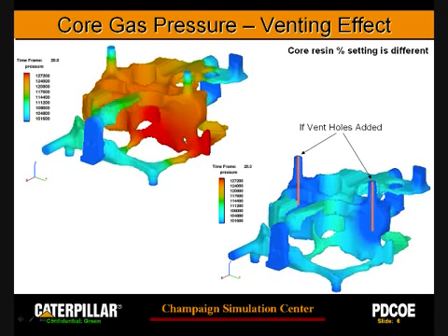That means most likely during filling you have a lot of bubbling, and even after the end of filling you still have bubbling. I think a gas bubble during filling is probably slightly less of a concern. Especially when the mold is full, you may form some kind of skin on the top, and then gas bubbles form underneath. That will be a problem.